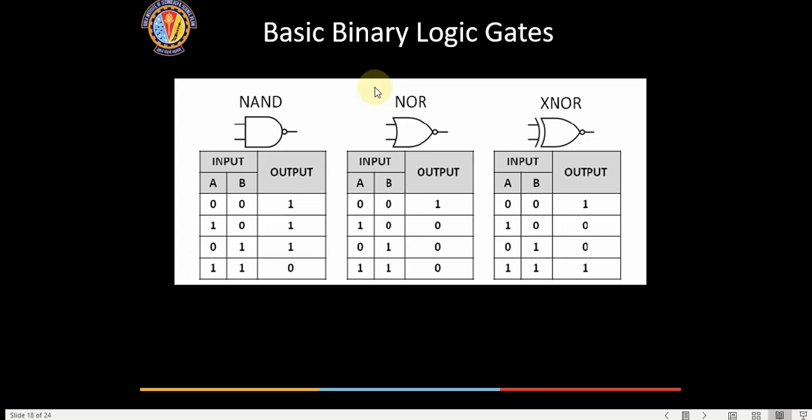Okay, so when we read about the circuits towards the end of the course, I'm going to cover how this NAND gate functions internally, because you have not yet done the microelectronics course. Once you do that, we will dedicate a few classes towards the end to understand how these gates work internally. Just understand that to synthesize an AND gate, it is always a NAND gate followed by an inverter, right?